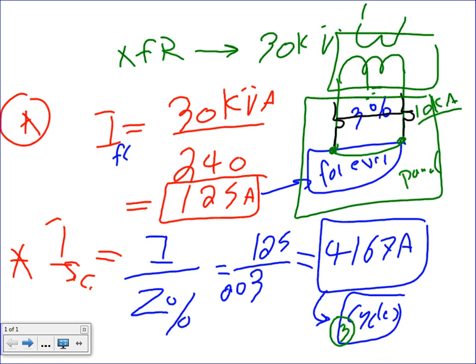The exception is 230.2(A). If you have a fire pump, on page 73, they give you an extra service for it. If you have an emergency system, no problem. Legally required standby system, no problem. Optional standby system, no problem. Power production and systems designed for connection to multiple sources. These are more in the commercial industrial, guys, but for the most part, you can only ask for one service to your building.